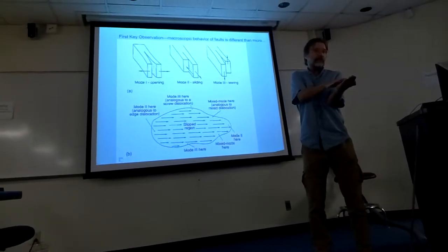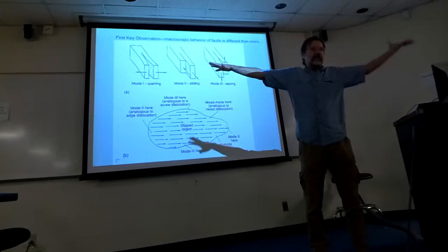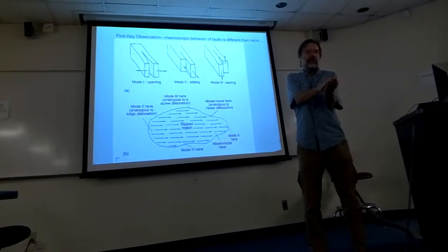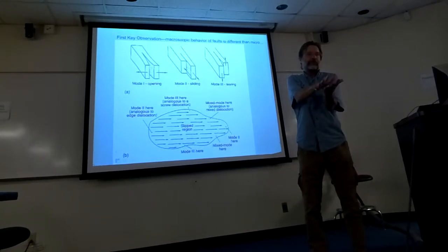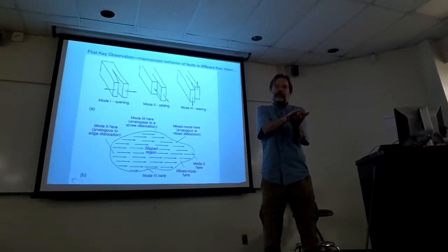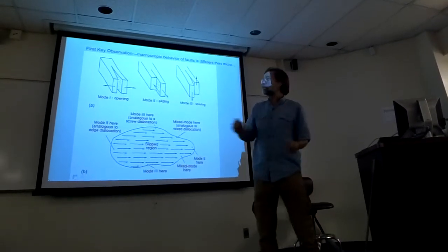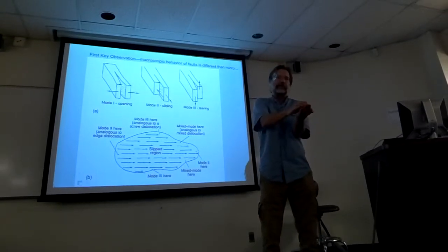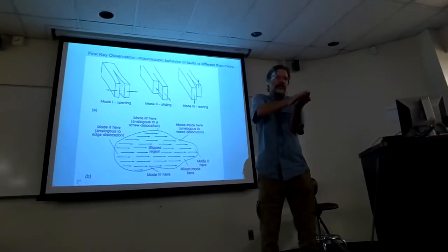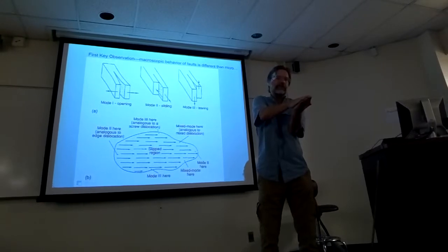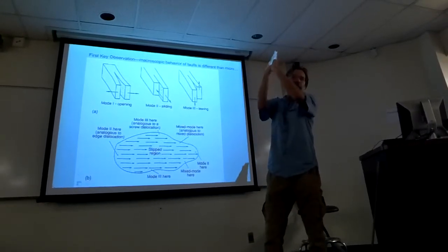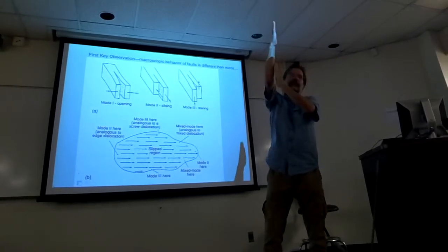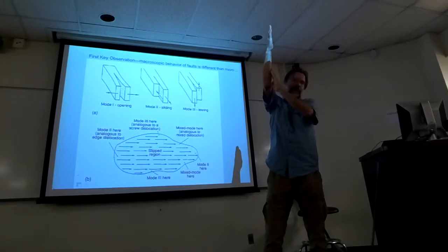If a fracture is forming within a material, it doesn't instantaneously fill the world, right? So as a fracture forms, or as a discontinuity forms, it propagates, just like the fracture on the windshield. But when it's in shear mode, the stress concentration is different depending on where you are relative to the sliding motion. And the tearing mode is the simplest one to see, because as the material starts to move, your hands, you can see that there's a scissoring effect. It's going to tear material in advance of the propagating fracture.